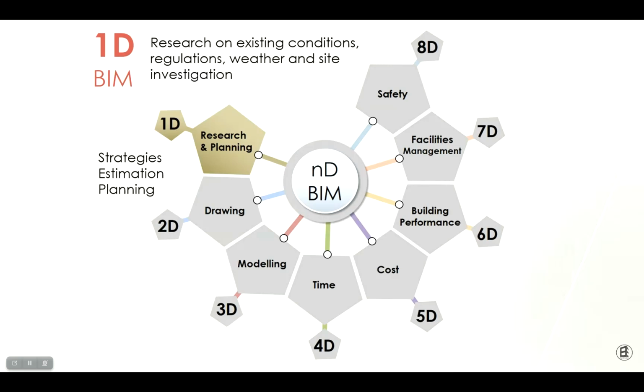Okay, just like I told you, estimation and costing is going to be important, and we have studied it in our civil engineering also. If we are calculating a wall width and length, you can calculate the number of bricks also, because we know the brick size. You can calculate the volumes, you can calculate the weight, you can even estimate the concrete materials in cubic meter.